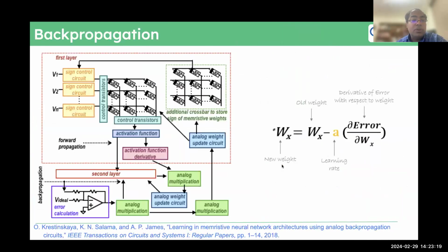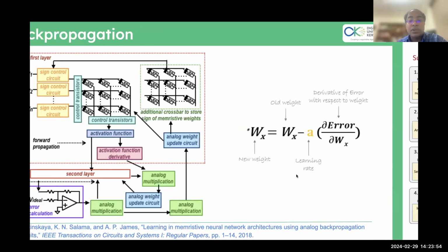Now, another thing that we looked at is whether it is possible to really build on-chip learning, and can we do that in analog compute and build various blocks related to that with these crossbars. And this was one of the early works on backpropagation, how you can build the entire feedback kind of networks, everything in analog, and you can place this close to the sensors. Which means you can have online learning next to the sensors without sending it to complex compute.